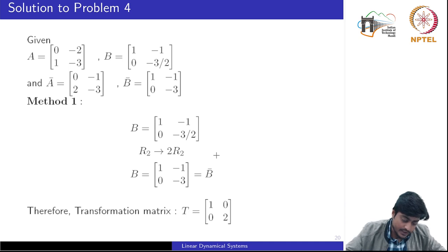So here we have listed two methods to find out whether these two pairs are equivalent or not. In the theoretical results, you would recall the key ingredient is to find the transformation matrix T or P, so that these A, B pairs are related by that transformation. Those transformation matrices could be obtained in a number of ways.